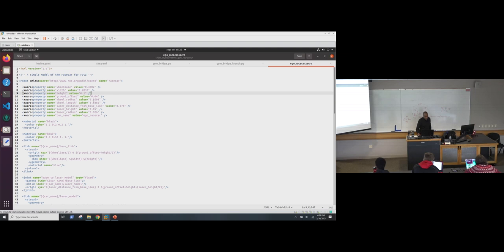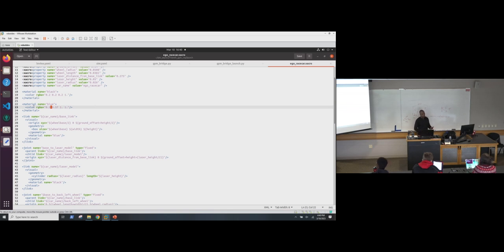And this is all your information about the actual robot here. These are like variables, and they're used in this file here. So this is a universal format for describing it. They just made it black and blue. You could change the color, it doesn't really matter. But you can put material properties in there. They didn't add a lot, but you can put masses in here if you're trying to do more simulation, like if you want to go into a curve or use momentum to figure something out. So you can add a lot more into this, but right now they're just using color. It depends on how advanced you want to get with that.